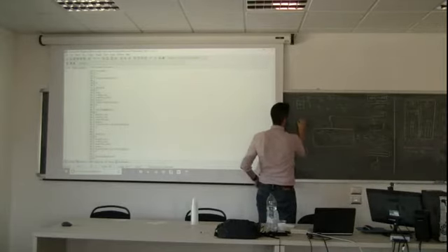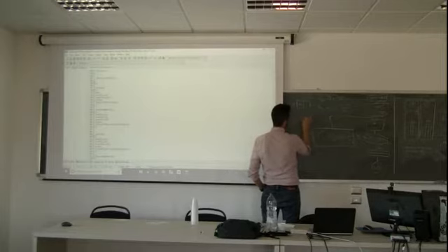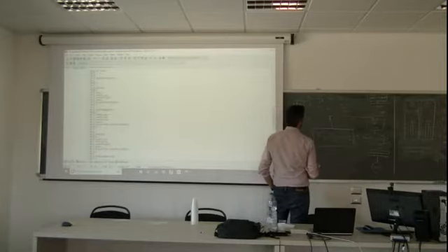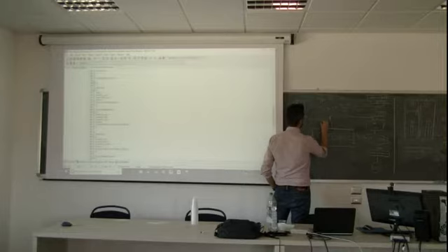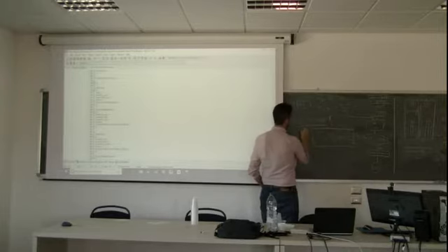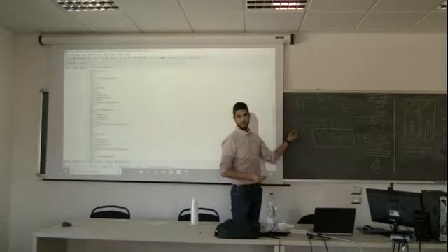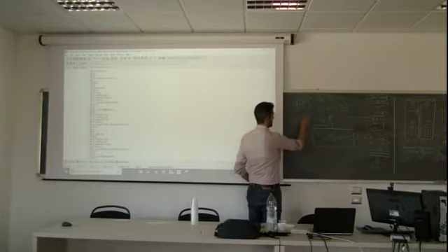TP is K divided by delta x1, multiplied by TE, plus QB delta x1 divided by 2, all divided by K divided by delta x1.